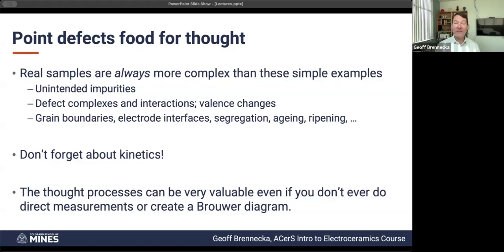We were avoiding any phase segregation. So I talked a little bit when we were looking at the very first example of aluminum oxide doping magnesia, about how you could actually drive the alumina to precipitate out using Le Chatelier's principle, going back and forth with that reaction. Those kinds of reactions are possible, and that kind of control is possible.